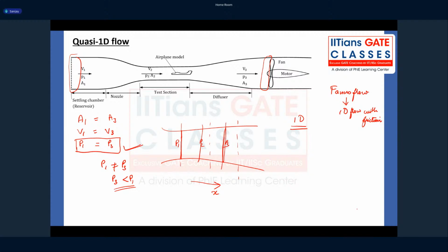What did you say about it being inviscid? So see, I will come to that point in our classes, Danesh. But there is a viscosity of air, right? It is very less. You can assume it to be inviscid, but there is some viscosity, and that viscous effect becomes dominant close to the walls of the tunnel. So if you see the test section, when the air passes through the test section, you can see that there is a boundary layer growth.